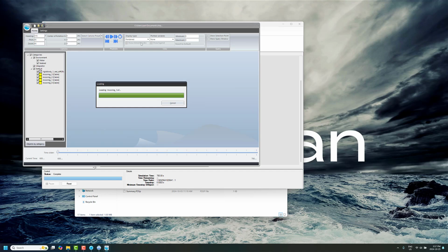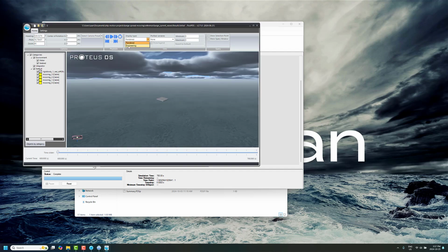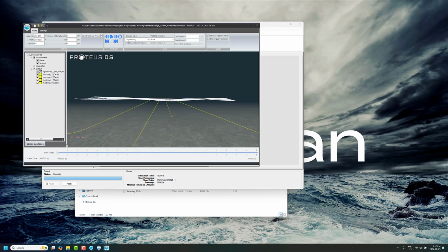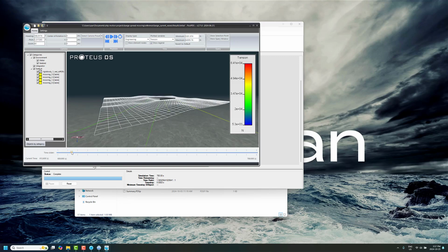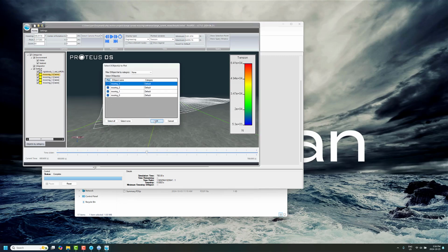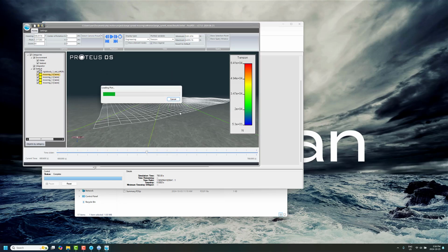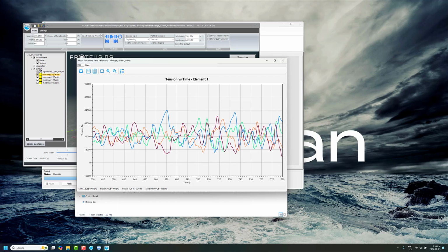You can look at the engineering view, and it shows things a little bit easier. If you like, you can show the tension range in here. You can see the barge riding through the waves, and there's a current imposed on top of that as well. This plotting feature is really nice to look at all of the line tensions together in one plot. This is at the top, not at the bottom of the mooring. It's only showing what we've loaded here, but it's really nice to get some idea of the variation.